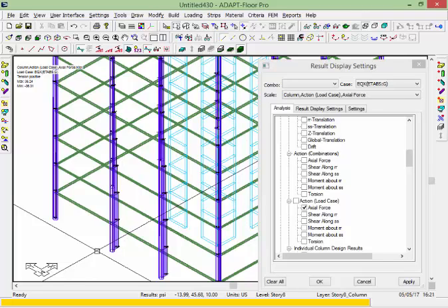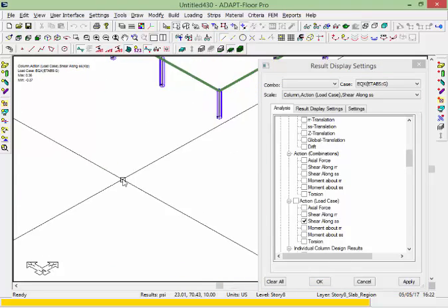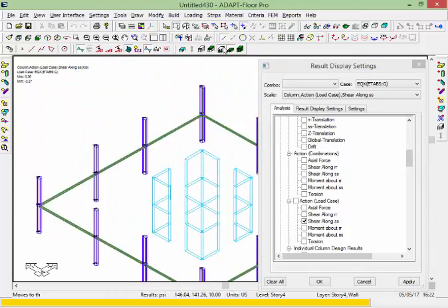You can always analyze a structure for lateral and gravity within Builder, but that is a possibility. That's one reason you would bring in reactions from ETABS through the integration console. And you can see we have shears in both directions. I'll go ahead and go to single level so we can see that a little bit better.